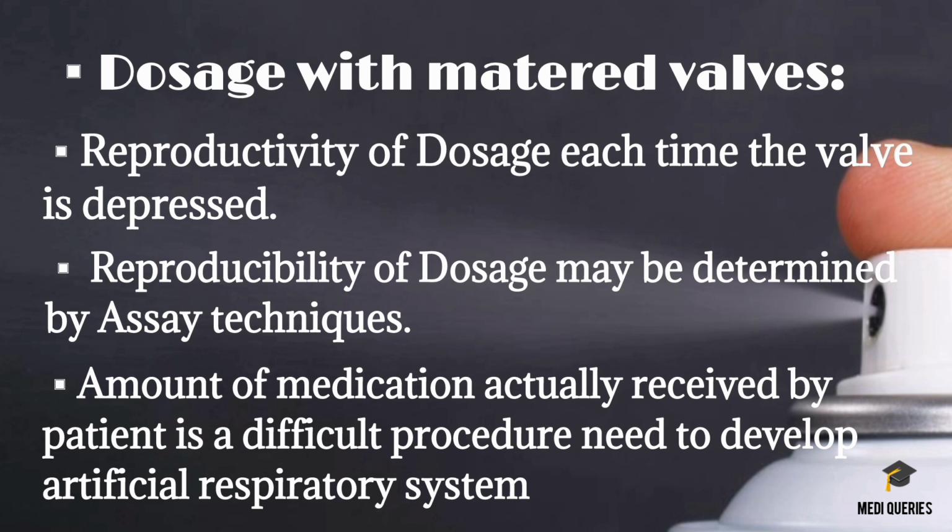Another method that can be used involves accurate weighing of the filled container followed by dispersing of several doses. The container can be reweighed and the difference in weight divided by the number of doses dispersed gives the average dose here. This must then be repeated and the results compared to determine the doses of the product.